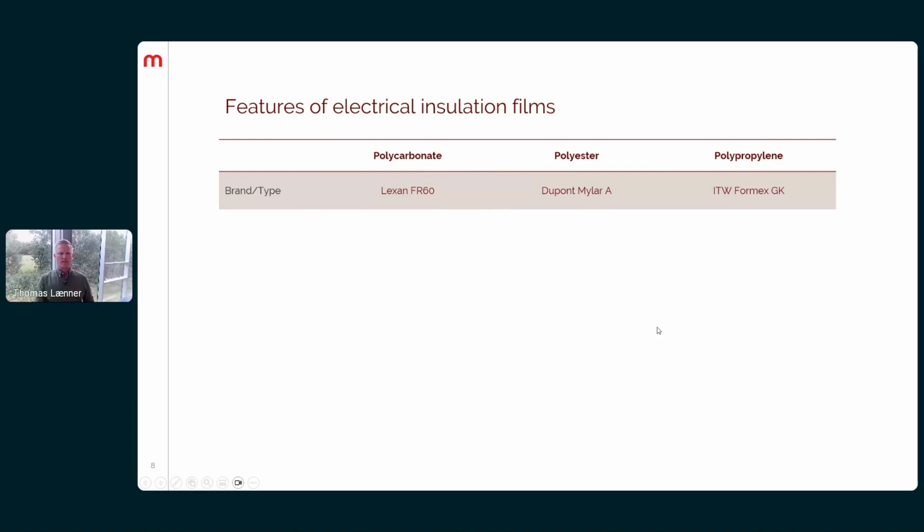One of the first requirements that customers normally specify for insulation film is the UL94 rating. It is part of the UL 746C testing, and it evaluates the polymeric material used in electronic devices. It states the fire behavior and resistance by testing against ignition and burning time. And the thing to notice here is that the lower the value, the better the flame resistance.